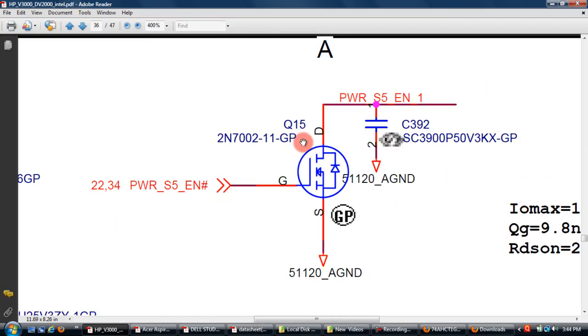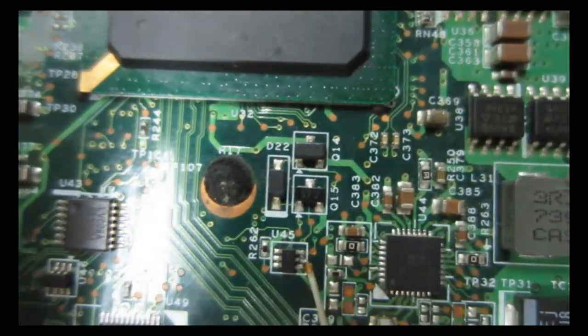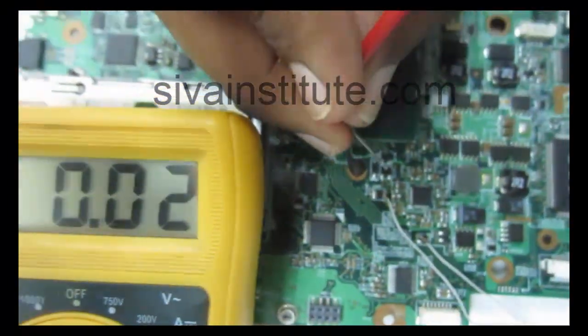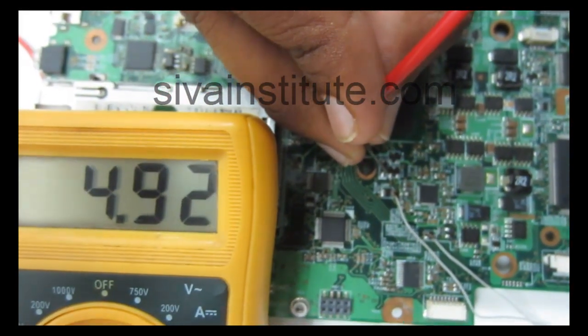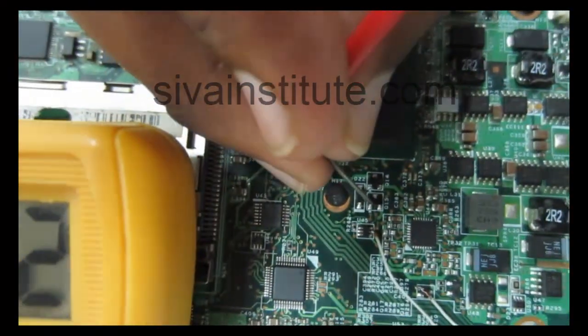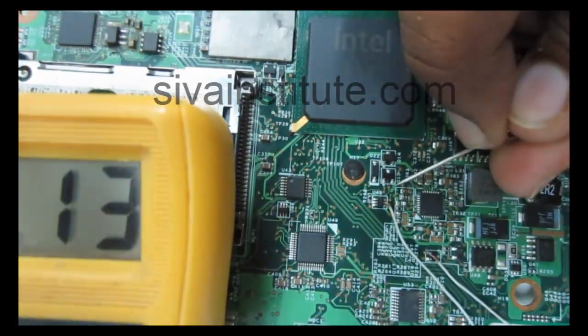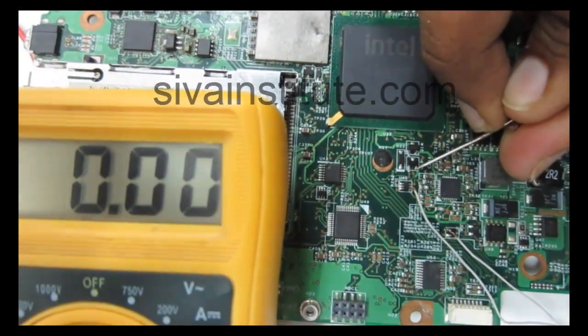See here, this is Q15. Without the SPI command, gate voltage is 5 volts, drain voltage 0. With the command, this voltage goes to 0, and this voltage comes out from this drain. This is the Q15 transistor. We will see the voltage without the SPI command. First gate voltage 4.9 volts, drain voltage 0. Source voltage 0. Source is already grounded.